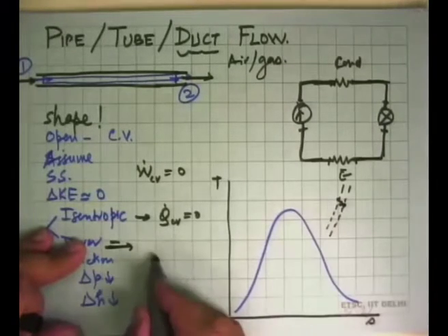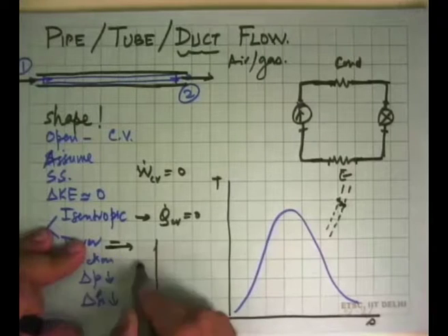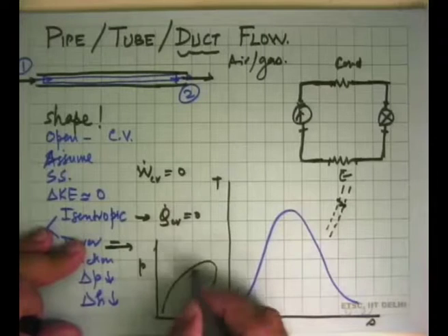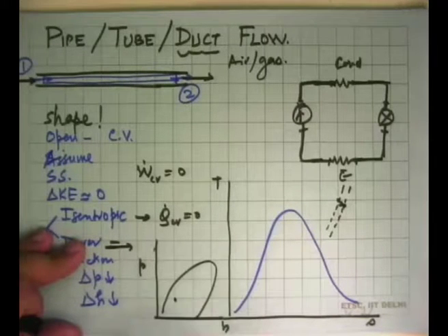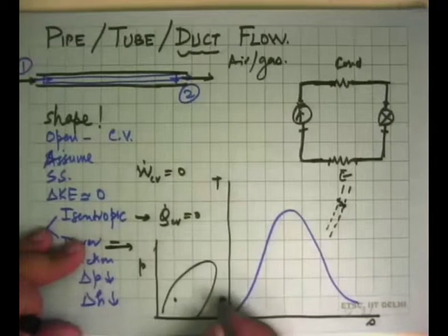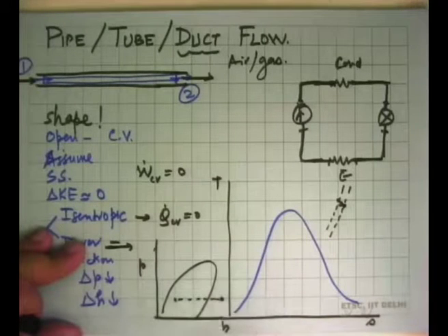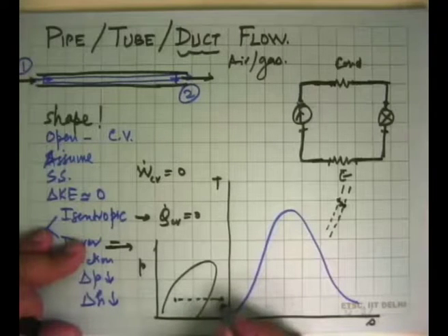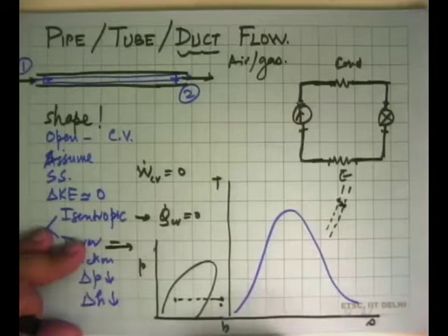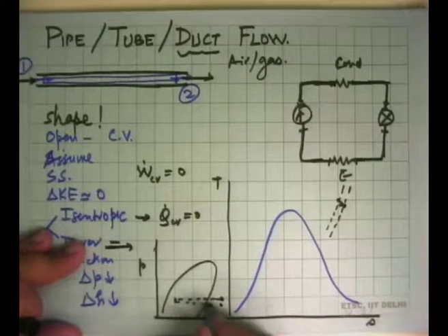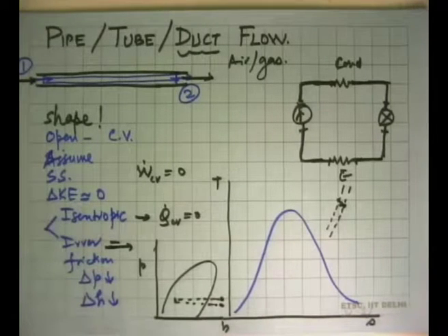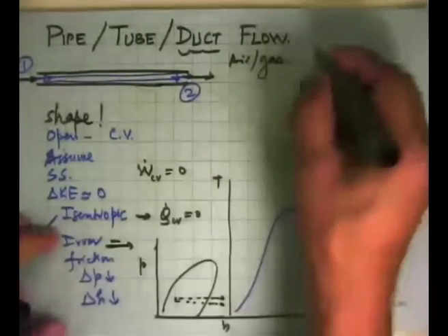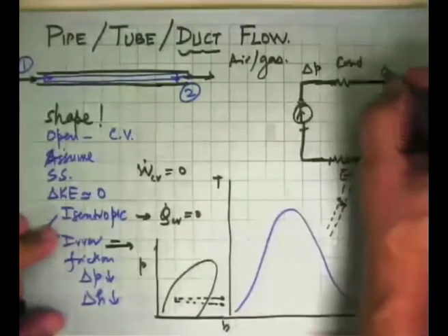On the PS diagram, when we have the dome there, we say that okay, we are pumping it through the evaporator from here to there. Ideally, we assume it to be a constant pressure process. Practically, the pressure will be slightly less, and so the process will actually be something over there. So in practical design of these types of systems, we will take care of the pressure drop in every one of these pipes.